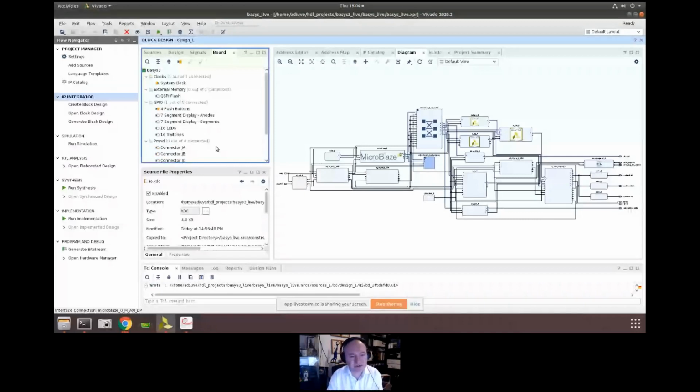Because we're using a specific driver block that I've written. We're not using that, because if you pull that across, all it will pull across is GPIOs for you to write and control in software. And I've actually written an RTL block that makes it a lot easier. In essence, with my RTL block, you just pass it the number you want to display, and it will display it. Whereas if you pull those two across, you would have to work that out for yourself. We're not doing anything with the QSPI memory in this one, so you don't need to do that.